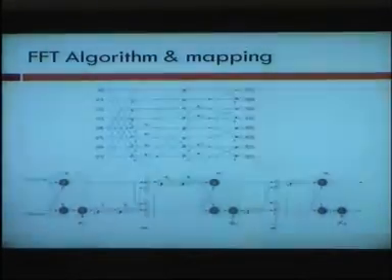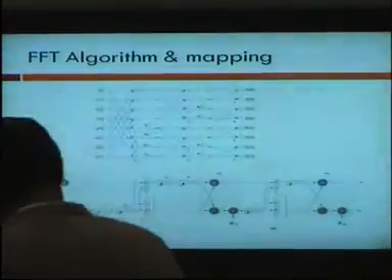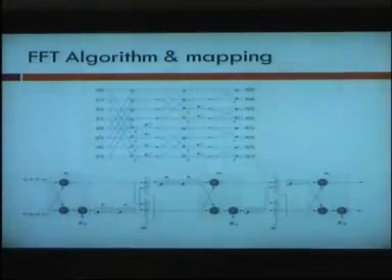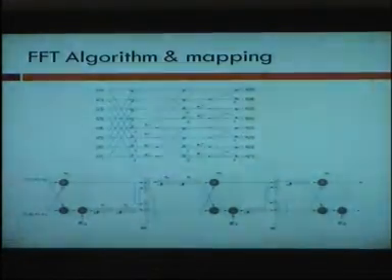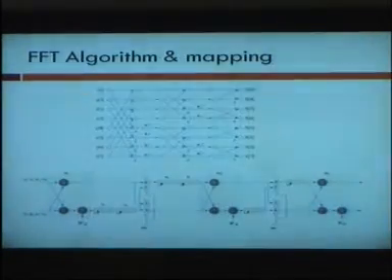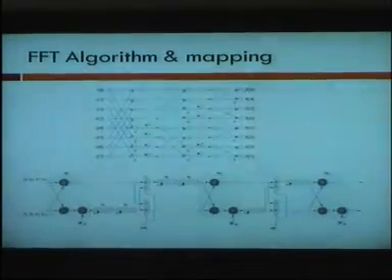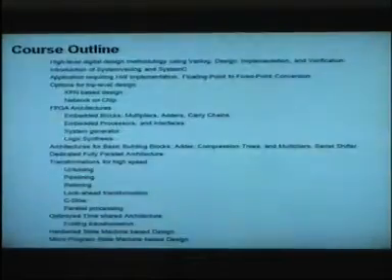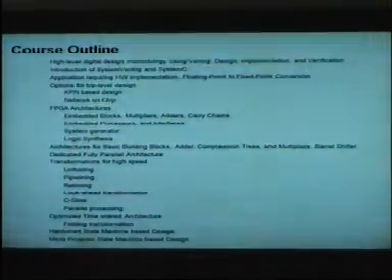So that's where the challenges are in the design, knowing how much folding of an algorithm you need to do is quite challenging. Sometimes you can come up with an architecture where data will flow smoothly, but in most of the cases you need to manage your data. You need to bring the data to the right part of your architecture at the right time. We'll spend more time learning about the folding, and then that'll take us to designing state machines in hardware, and then microcoded state machines.